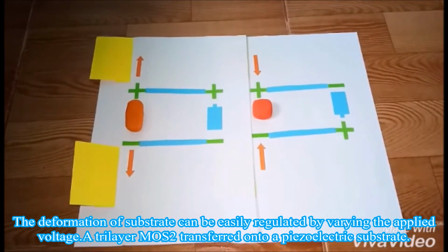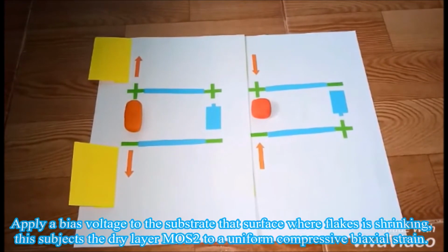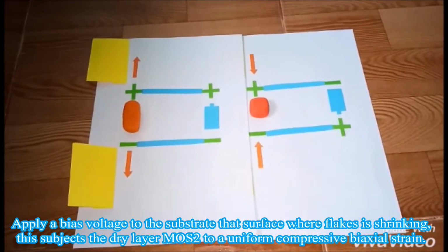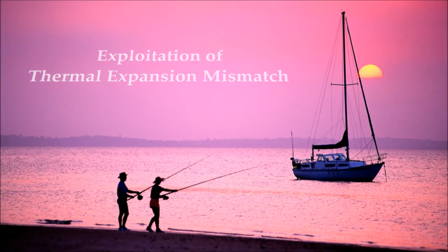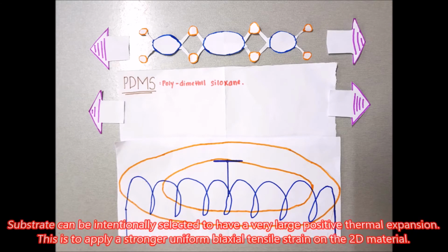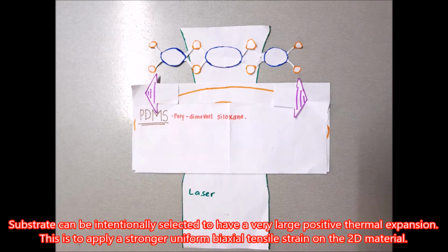A trilayer MoS2 was transferred onto a piezoelectric substrate. Apply a bias voltage to the substrate, and the surface where the flake sits shrinks. This subjects the trilayer MoS2 to a uniform compressive biaxial strain. 2D materials typically have negative thermal expansion coefficients. The substrate can be intentionally selected to have a very large positive thermal expansion coefficient. This is to apply a stronger uniform biaxial tensile strain on the 2D material.